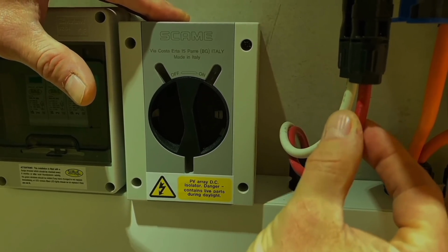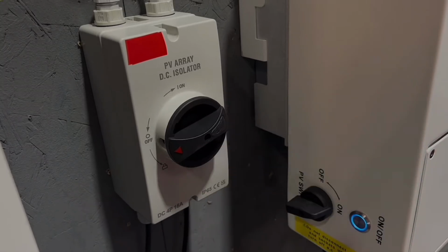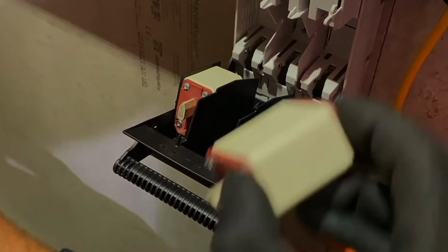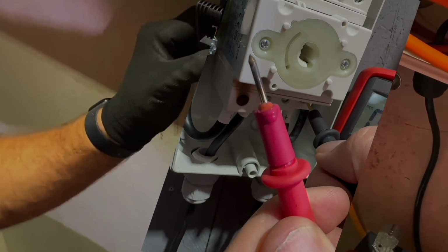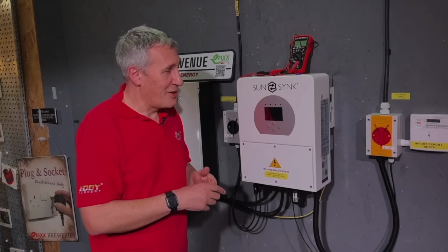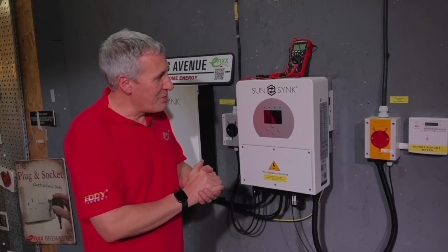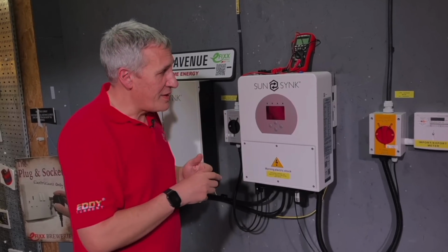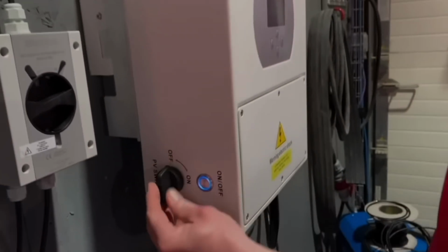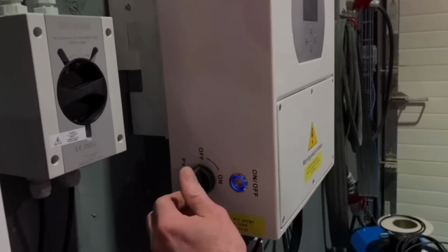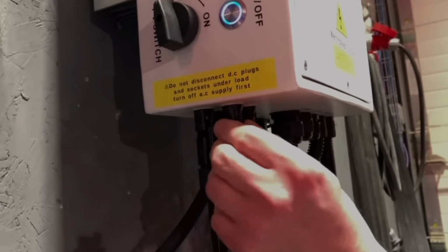An isolator is also required for the batteries from the inverter and needs to be located between the inverter and the protective devices of the batteries. It is also critical that we use DC rated isolators due to the significant arc flash which occurs when switching DC components. Finally, an isolator for the PV array. This has been covered by Gordon in a separate video where he goes into more detail about why we should not be installing DC isolators on the PV array if the inverter has its own isolator on the chassis. Not to mention the ability to remove the MC4 connectors, which requires a tool.